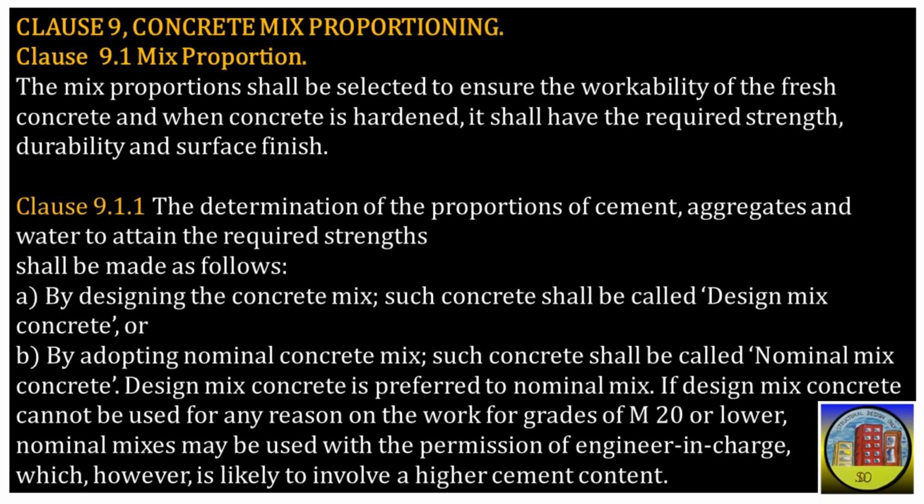Design mix concrete is preferred to nominal mix. If design mix concrete cannot be used for any reason on the work for grades of M20 or lower, nominal mixes may be used with the permission of engineer in charge, which, however, is likely to involve a higher cement content. Now the question may arise, what is design mix concrete and nominal mix concrete?